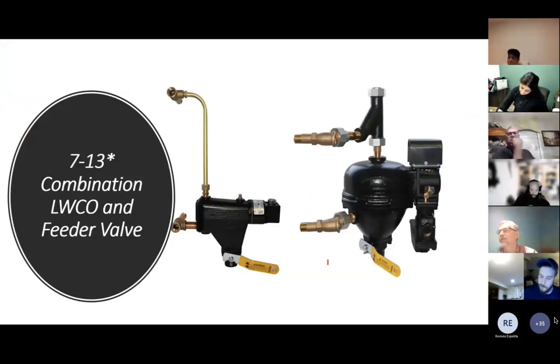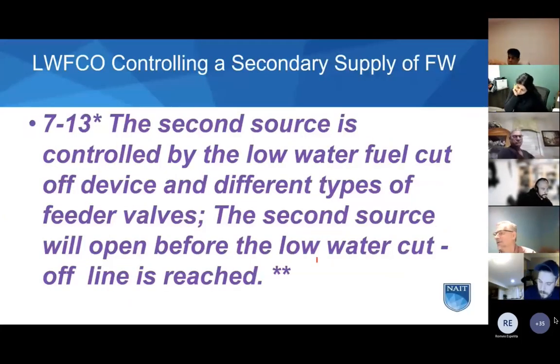Combination type. So just a couple of the devices you'll see out in the field. If a device like the float operated one we saw has a second source of feed water controlled by low water fuel cutoff and different kinds of feeder valves, the second source should open before the low water cutoff one. So if we have a backup source, this mostly applies to hot water heating, and